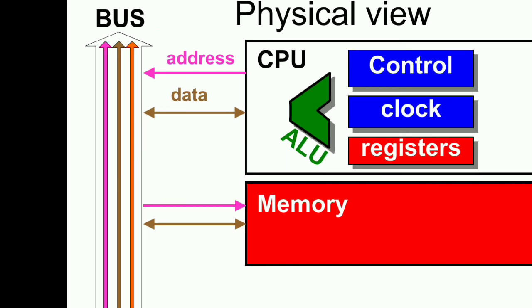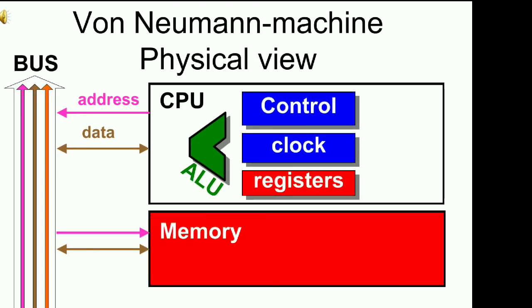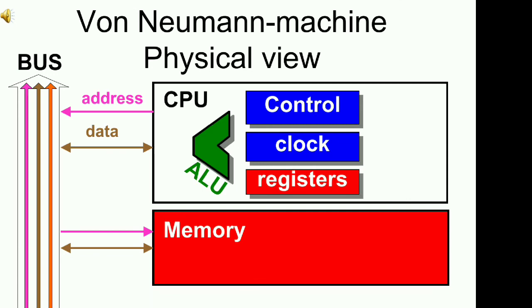And one more point: how many wires are in the data bus? It depends on the processor, on how many bits the processor is. If it is a 16-bit processor, there will be 16 data lines, 16 wires in the data bus. If it is an 8-bit processor, 8 wires will be in the data bus. So an 8-bit processor will have an 8-bit ALU, a set of 8-bit registers and 8 data lines in the data bus. This is how we have to keep adding to our knowledge about the processor.